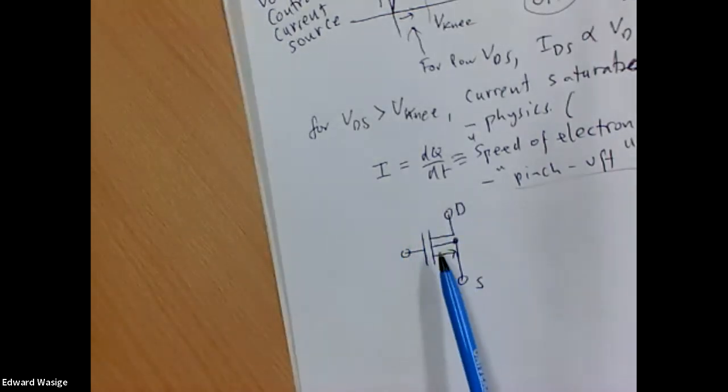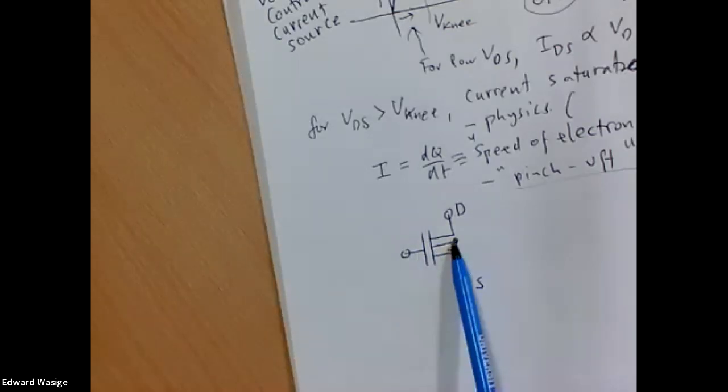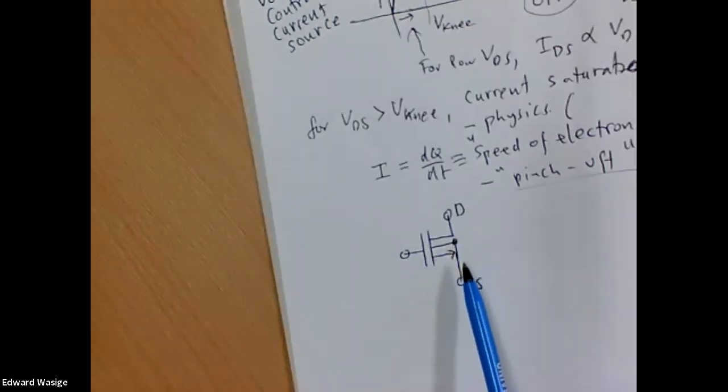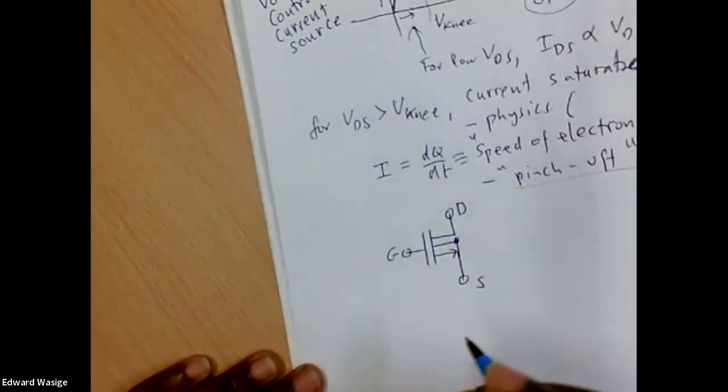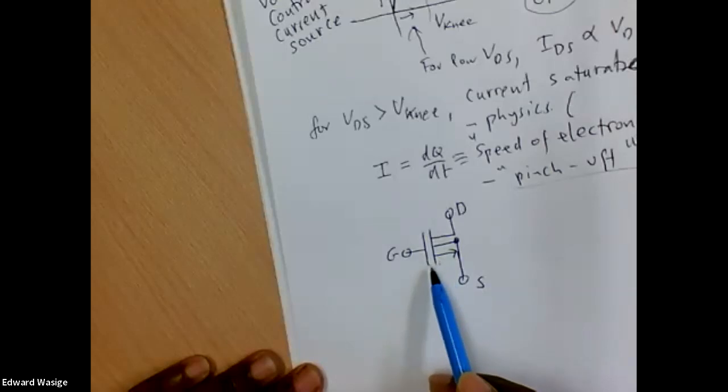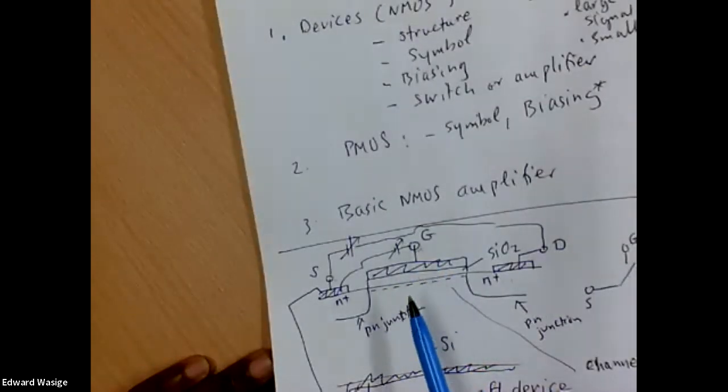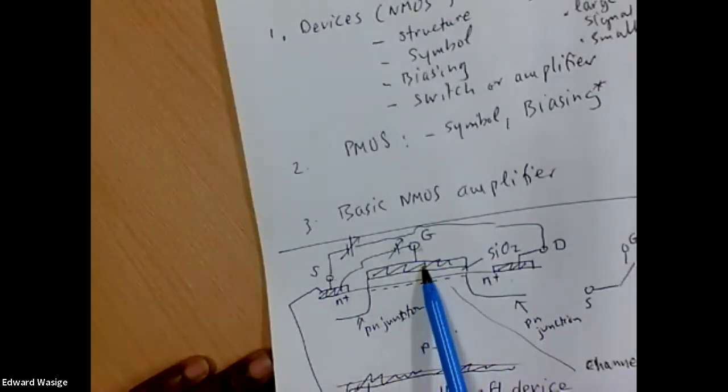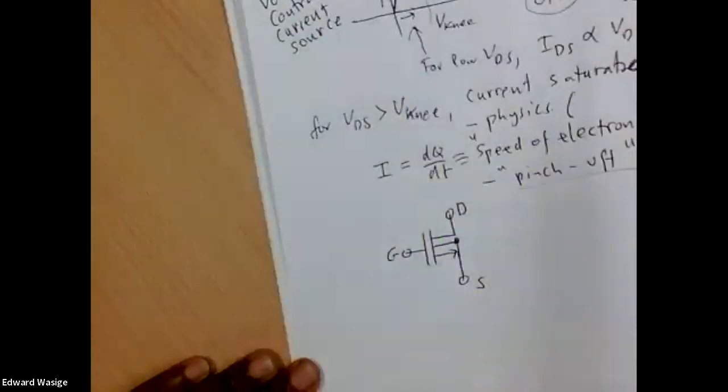So actually, when you do your lab, you'll find that your transistor is 4-terminal. For the NMOS, the body will always be connected to the source, and that's the gate. And you have these two lines which correspond to the gate region. You have an insulator there, SiO2, that's the gate, and that's a semiconductor. So this looks like a capacitor.